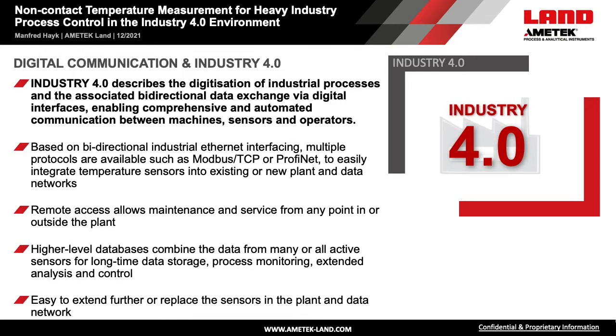Based on these bidirectional industrial Ethernet interfaces, multiple protocols are available, such as Modbus TCP or Profinet, to easily integrate temperature sensors into existing or new plant and data networks. Remote access allows maintenance and service from any point in or outside the plant, and also monitoring the process remotely.